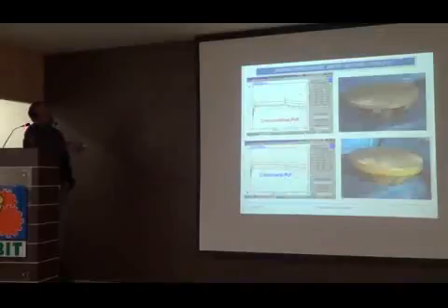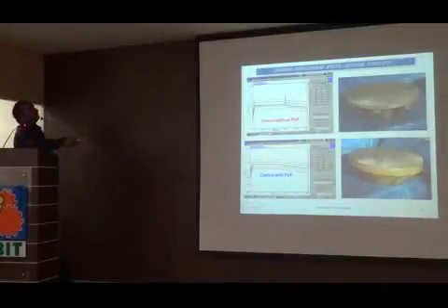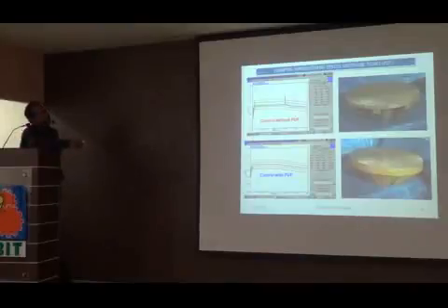And there was one of our elements in the vibration where we were not able to control the input, and there was one peak coming. See, this is crossing this red line, which was not allowed. Crossing the red line means it is the abort line, where the system will fail or trip. So to reduce this peak, we have to bring it down. For that we enhanced it by improving damping. That is, we use something called polyurethane foam. We fill it around this so that damping is introduced into the system. So the peak has come down from here to here. This is how we could use this system.